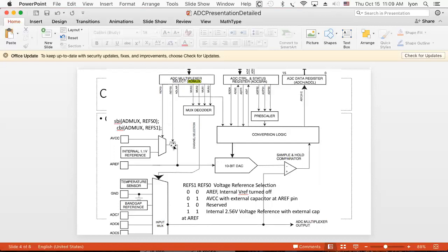And that is your voltage reference input. You can see how an analog reference, if left unconnected, will be overridden by whatever comes out of this 2-to-1 multiplexer. And with a 0 being written into REFS1, we can see the 2-to-1 multiplexer is going to select leg 0, which is AVCC.